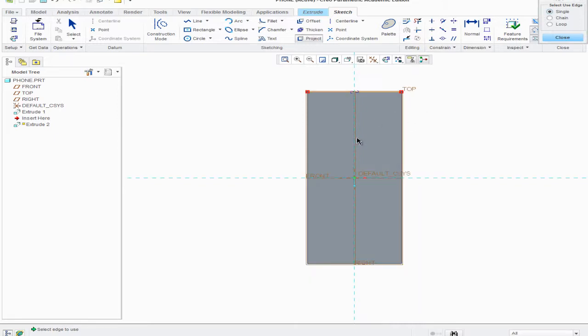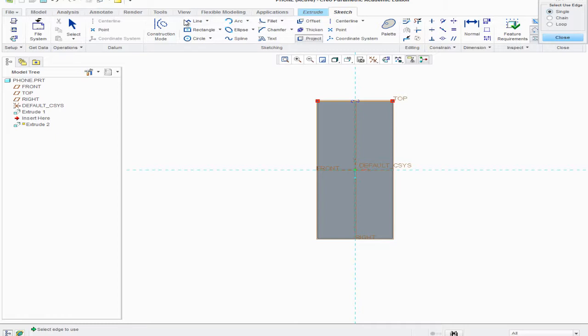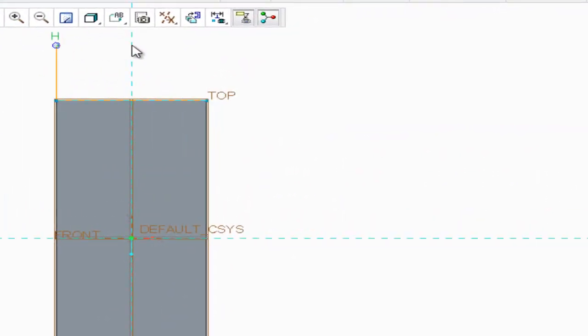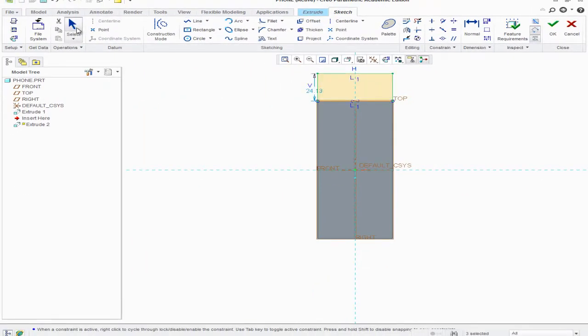on our drawing. So I can just zoom out a bit, go up to my line tool, I'm going to go up, doesn't matter how far, across. When I get L1, I've got 2 L1s appear there, it just tells me that the 2 lines are exactly the same length. I'm going to go back again, and then to finish, middle mouse click. Now, like before I said, Creo will automatically dimension the size of that. So clicked on the select, it's gone yellow. I'm going to select the dimension that I want it to be, and I'm going to put in 18.